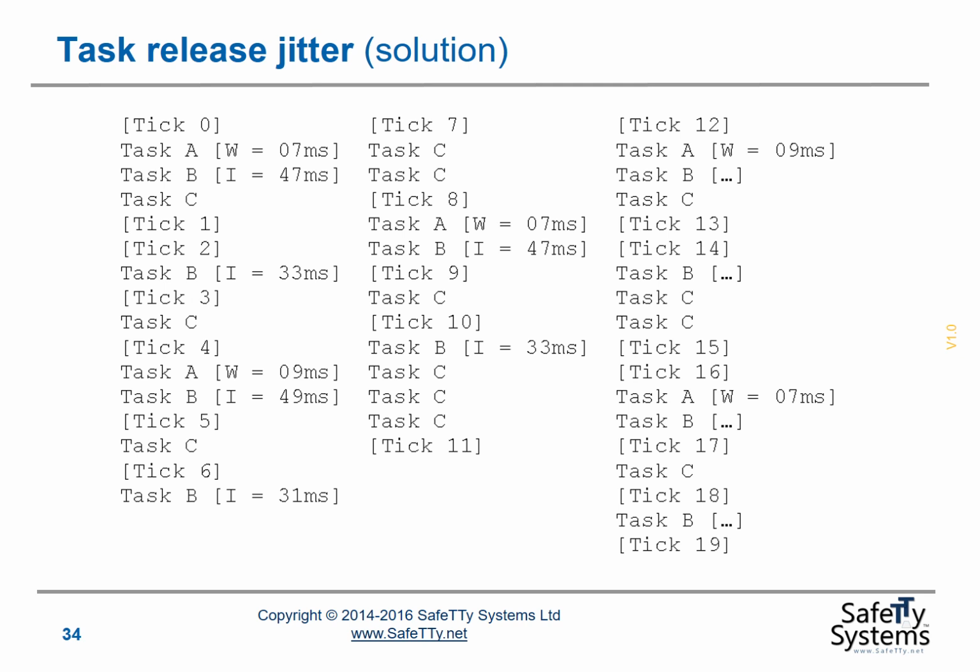Note here we're saying at the start of the tick list the interval between the releases is 47 milliseconds. That's because we're measuring that release time from the last time that task B ran at the end of the previous tick list. So we're assuming it's a continuous sequence of hyperperiods that we're running here. The other thing to note here is that when you see the ellipsis, the 3 dots, that means the data are just the same as previously, so we don't need to consider them.